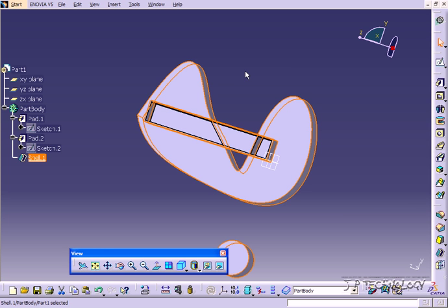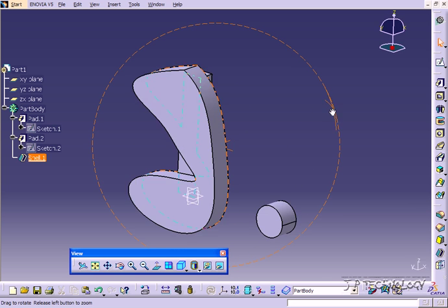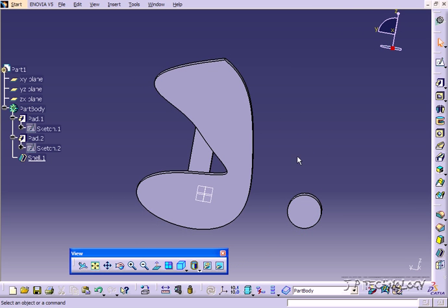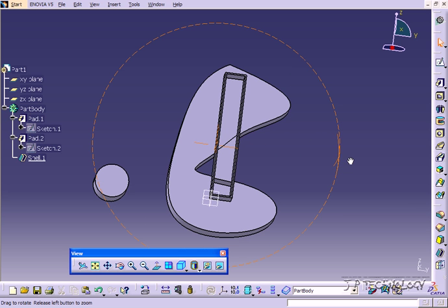If you have a part, you're able to shell and make the negative for it. Like I have here, I made a unique profile and design, not something that you would want to go back and slowly create a minimum thickness for and shell out. Using the shell feature, it allows you to create that negative quickly and easily.